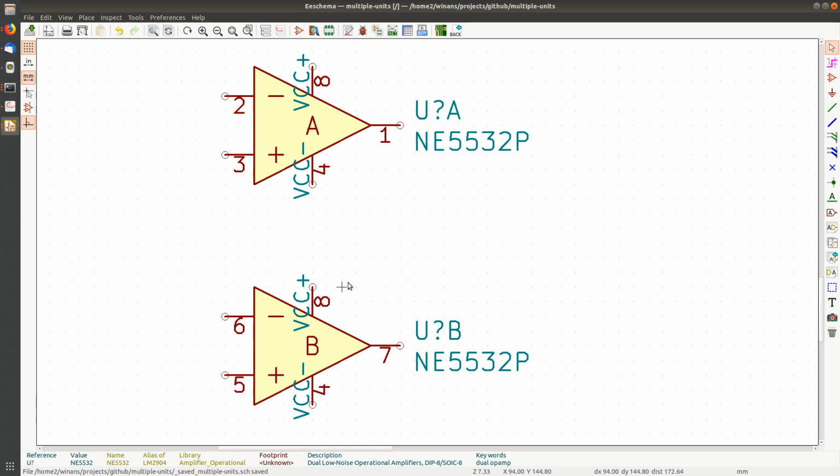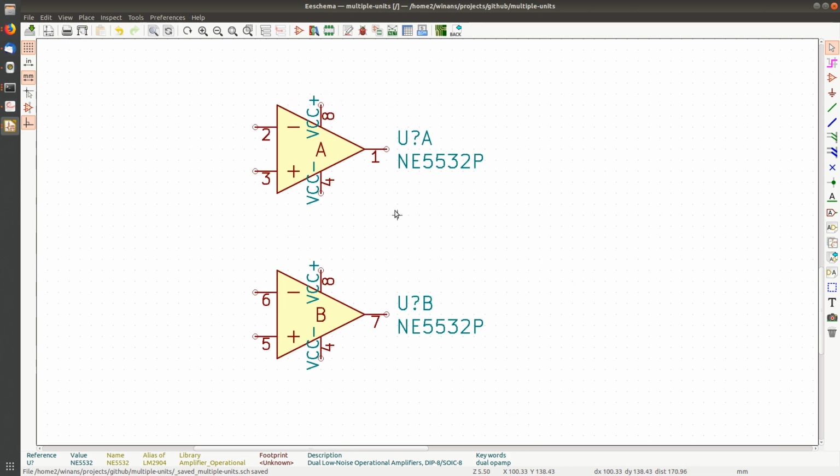So again, this is where we need an overview before we dive in and design one of these. We need to see where we're going, right? So in this particular variation, it has 2 pin 8s. So when you do this in KiCad, you have to have, symbolically or directly physically, both of these pin 8s go to the same net. And both of these pin 4s have to go to the same net. Otherwise, it's a design rule error, okay?